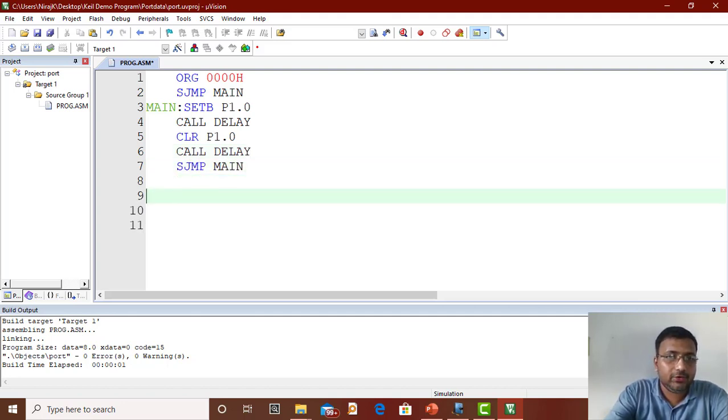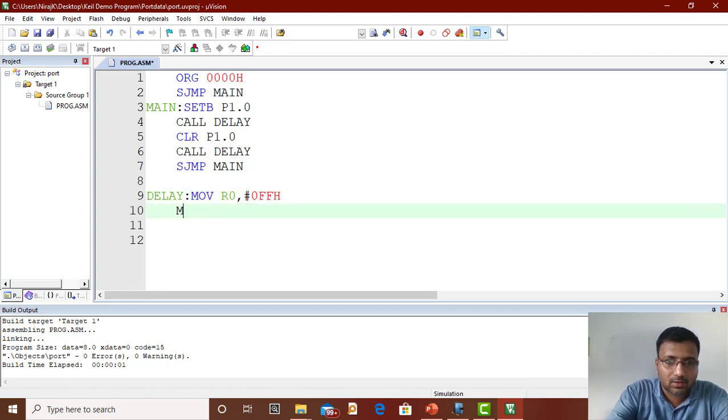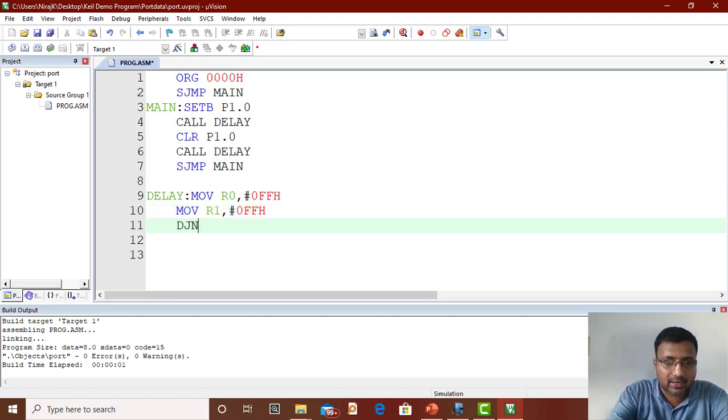I want to repeat this continuously, so I will call a delay, a little bit more delay now, so you can observe the delay and the waveform. MOV R0, #0FFH, MOV R1, #0FFH, DJNZ R0, here. My label will be here.